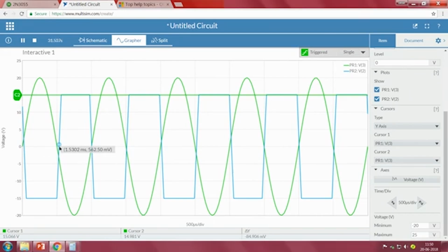Now, when you see, the thresholds are closely selected in such a way that it is always switching on and off within very small ranges. The reason is that in some biomedical applications, we are required to constantly maintain the temperature of the plant within plus or minus 0.1 degree or 0.05 degree variation.